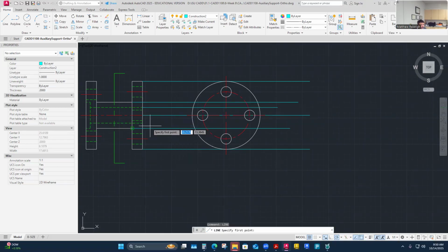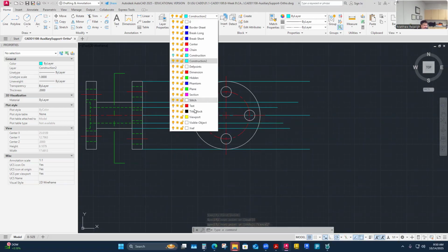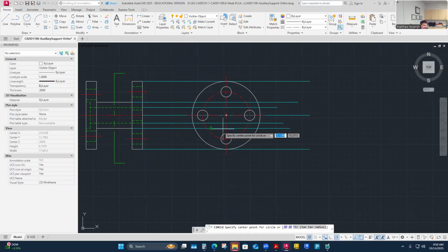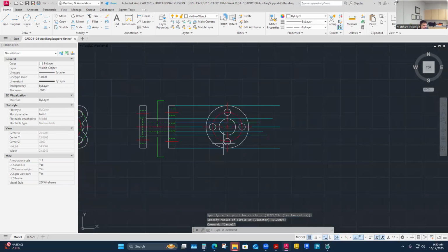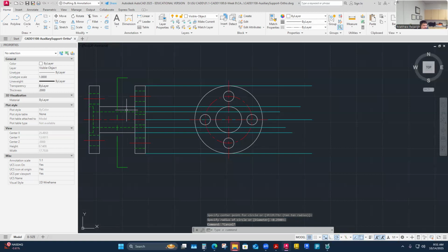So these are nice to know that I'm in alignment. I don't necessarily have to draw them on this way, but that'll kind of help me keep in alignment. Gives me something to pull like a simple circle to, as long as it's the right size. This should be 1.25 or 0.625 radius. That sounds correct. That should be the outer diameter, what we call the OD of this particular cylindrical feature here.